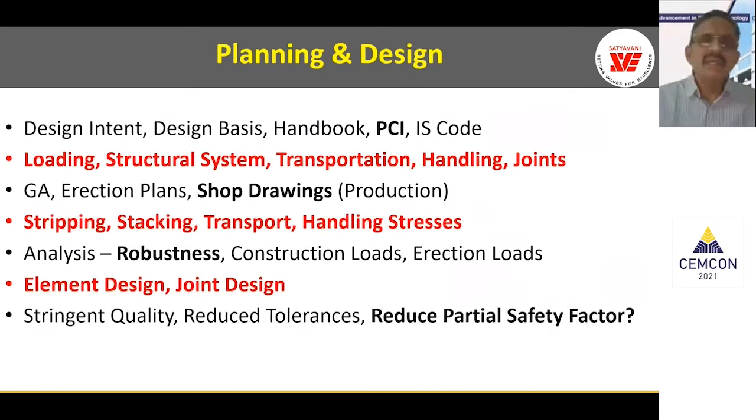So finally, in planning and design, as engineers, right from the conception of the project, we have to consider this method of technology depending on the time available and the size of the project to be delivered. For example, I get a client who is asking me to deliver a project within 1 year to build about 10,000 houses or 20,000 houses. I have to complete in 12 months. Then I have no other option but to choose precast, because I can eliminate all the uncertainties in delivery and also have the assurance of the delivery time, with the quality not being sacrificed.